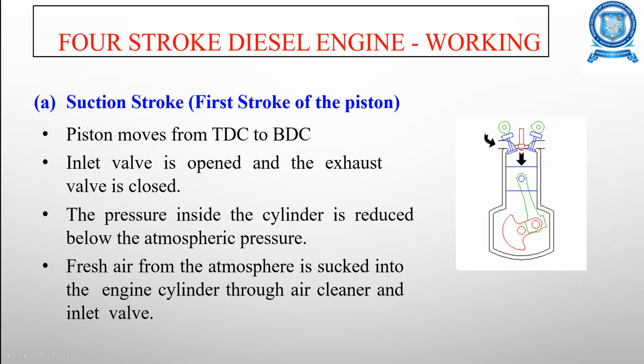The inlet valve will be open, but the exhaust valve remains closed. So the pressure inside the cylinder is reduced below the atmospheric pressure. Here only fresh air from the atmosphere will be sucked into the engine cylinder through the air cleaner and the inlet valve. That is the suction stroke.